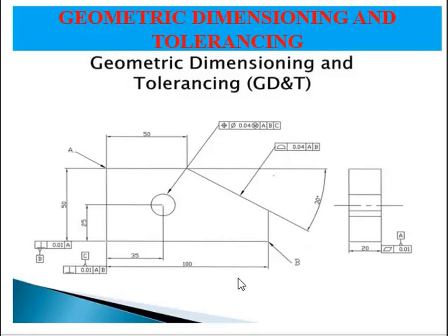So this is how your engineering drawing will actually look. This is the drawing of the object, which has been given some dimensions that we are able to read easily. It's like this is 100, this is 35, this is 50. The problem with students is they don't understand what these rectangular feature frames are talking about. So the motto behind learning GD&T symbols is to understand these rectangular feature frames.